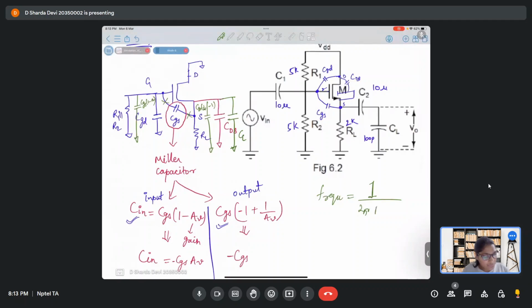It comes from the stability picture, where we have the S plane, and the negative side of the plane gives you a stable circuit, whereas the positive side gives you unstable circuits. So when we say negative frequencies, it is also regarding stability. But in our terms, numerically, we'll go for magnitudes only.